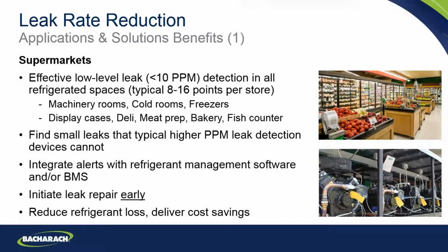It's also possible to integrate the alerts with the refrigerant management software and a building management system. The key thing there is doing something with the data. Once the leak has been found, it's important that it's acted upon and there is an initiation of the leak repair to get that leak early and get it before too much gas has escaped. So this can reduce refrigerant loss, this can deliver cost savings.